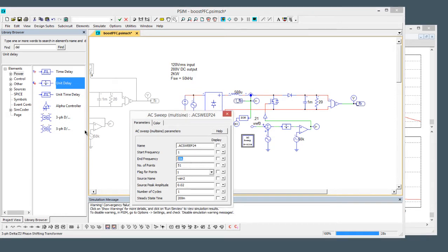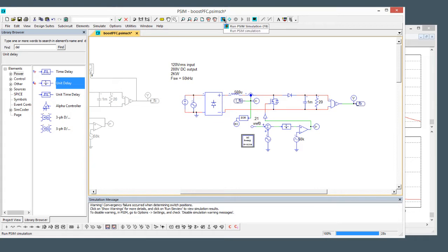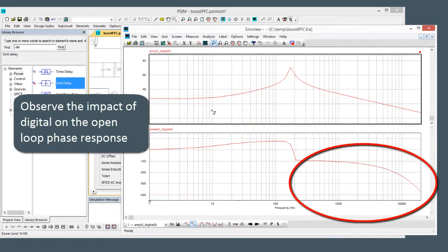And we won't sweep nearly as high, although I'll leave it, I'll sweep that high to start with, so we can see what the difference is here. So we'll run this simulation now, and we'll join back when it's done. So here's the digital output. We'll save this and then import this into SmartCtrl as well.